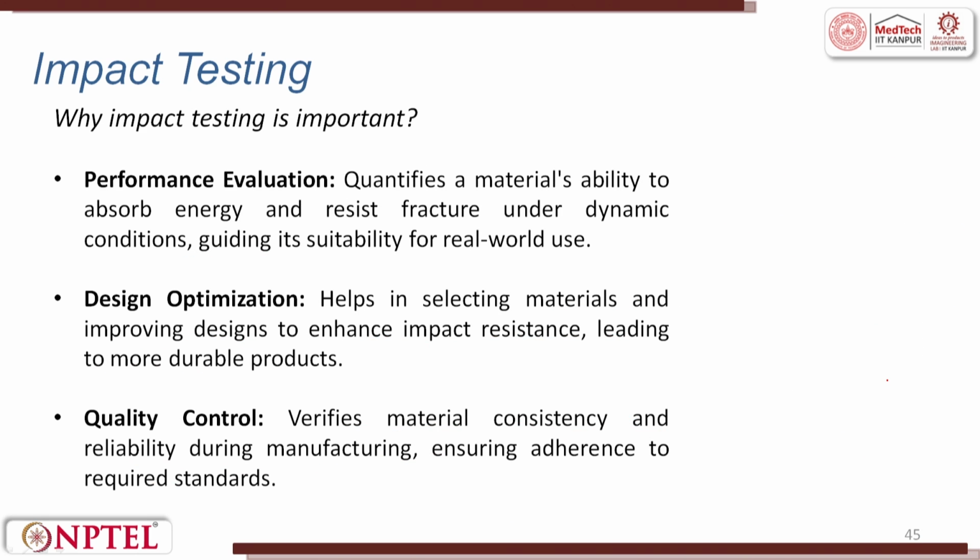Why is impact testing important? First is performance evaluation. This quantifies a material's ability to absorb energy and resist fracture under dynamic conditions, guiding its suitability for real world use. Wherever dynamic loading is there, impact could come, so the material is designed for its performance under these conditions.